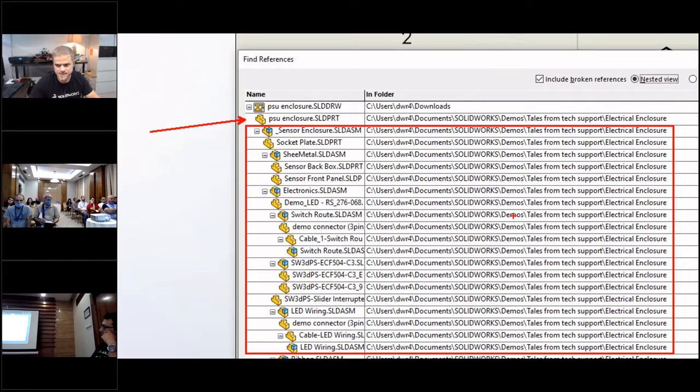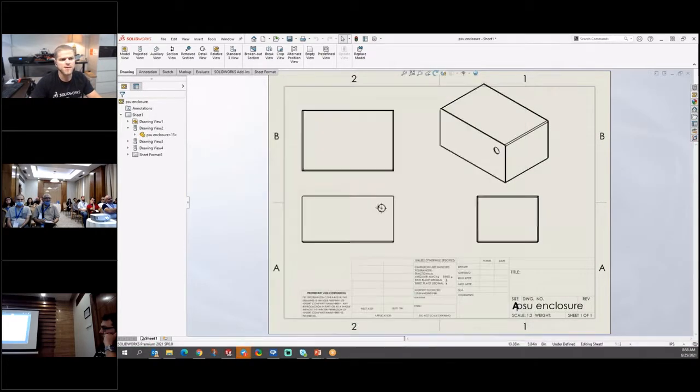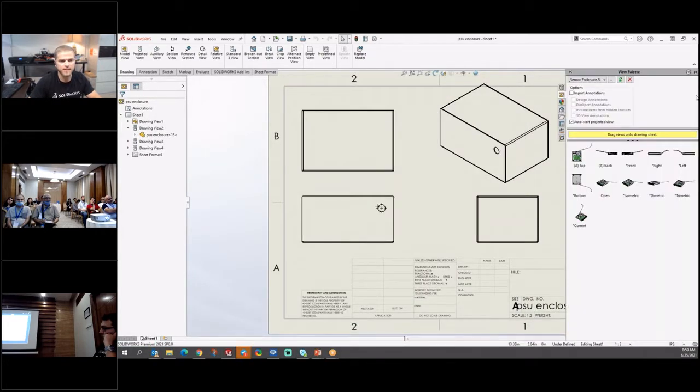And, you know, sometimes that's not a huge deal. It's not necessarily a big problem. But if you're using SolidWorks PDM and you go to check in this drawing, you go to place this drawing into the vault, and all of a sudden that drawing tries to pull in 200 other files with it, and that's where you go, hey, something's wrong here. I need to check into this.